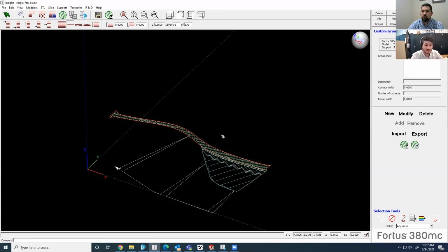It's not only an appearance concern, it is a function and mechanical property concern. So the UV actually breaks down the mechanical properties of the ABS. It becomes very brittle and no longer ductile or bendable. So I try to build in ASA as often as possible, unless ABS is explicitly requested by my customer.